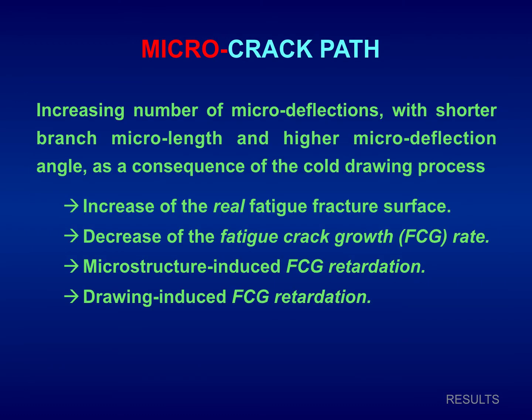As a summary of microcrack path, we have an increasing number of microdeflections with shorter branch microlength and higher microdeflection angle as a consequence of the cold drawing process. An increase of the real fatigue fracture surface, a decrease of the fatigue crack growth rate, microstructure-induced fatigue crack growth retardation, and drawing-induced fatigue crack growth retardation.